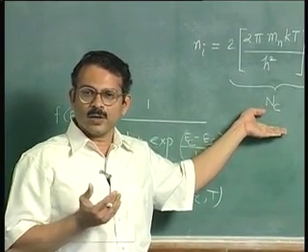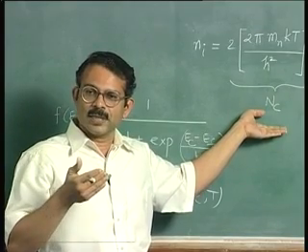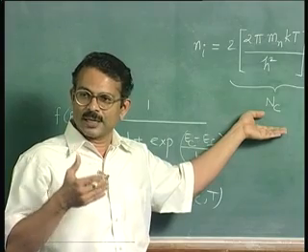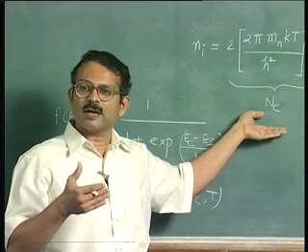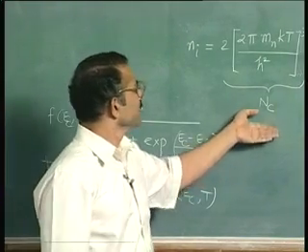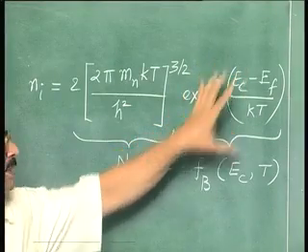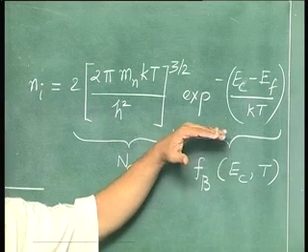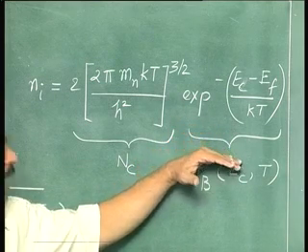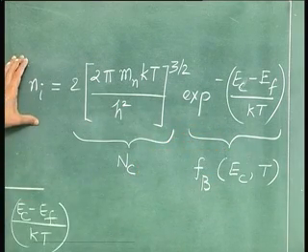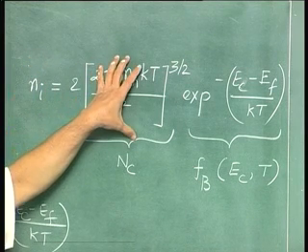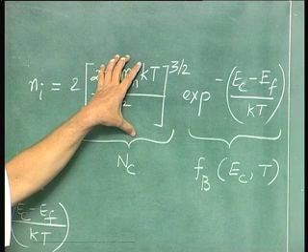When you work with the actual description and come up with a simple formula, and you want to physically interpret that formula in terms of some effective description, then since this term represents the fraction of occupied states at Ec at any T under the Boltzmann approximation, and Ni represents the number of occupied states, it is evident that this can be taken to represent the number of available states at Ec.